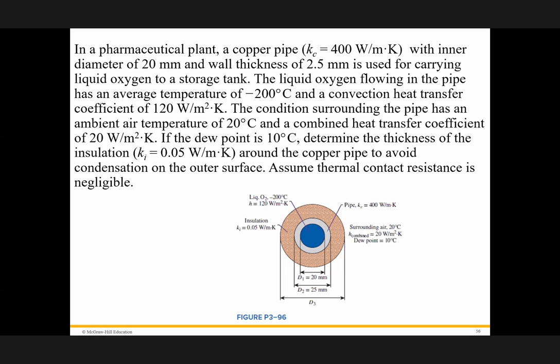Okay. I know the temperature of the ambient, but the problem here is the thickness of insulation is not given. Also, draw the thermal diagram, the resistance from pipe to the outside, to see what is given, what is unknown.